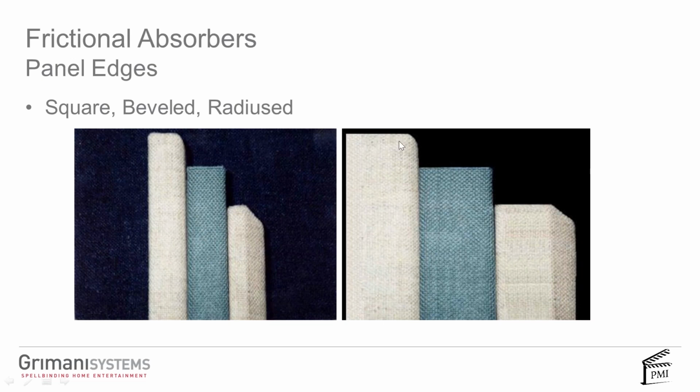So now, absorber panels come in all kinds of different shapes and forms and thicknesses and types and materials. They can come with rounded edges, square edges, beveled edges, whatever. I will warn you that most of the panels that have these sculptured edges are done by hardening all of the edges or putting a plastic form around them. That also means that this entire side is now no longer absorptive, which is a pity because you're losing between 15 and 20% of the absorption capacity of the panel. So if you can get away with the regular square panel with soft edges, you should try to do that.